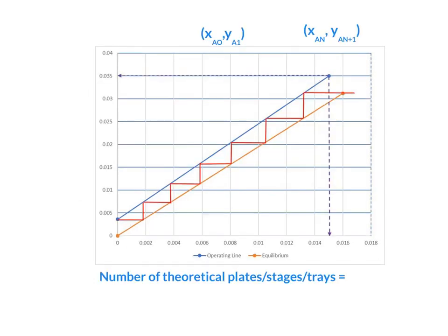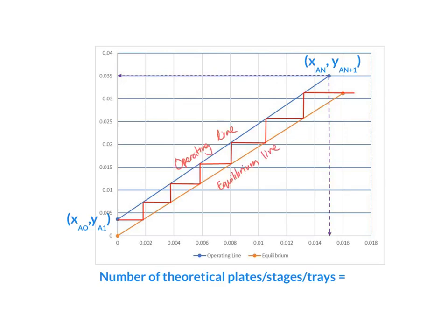So from the graph, we can label our graph. This is the coordinate for YAN. So we just move to this point and label the point. Next is to get the label for the bottom of the operating line. Next, what you need to do is start drawing your horizontal line here, then vertical, horizontal, vertical, until you reach the limit that we have. Okay, just continue our triangle.